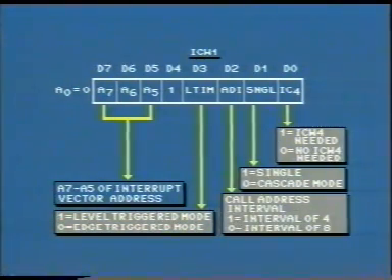If this bit is 0, then the interrupts are programmed as edge triggered interrupts. Bit D4 is at logic level 1 for the identification of ICW1. Next 3 bits D5, D6 and D7 provide the A5, A6 and A7 bits of the address vector of the interrupt service routines. ICW1 is loaded by keeping A0 at logic level 0.